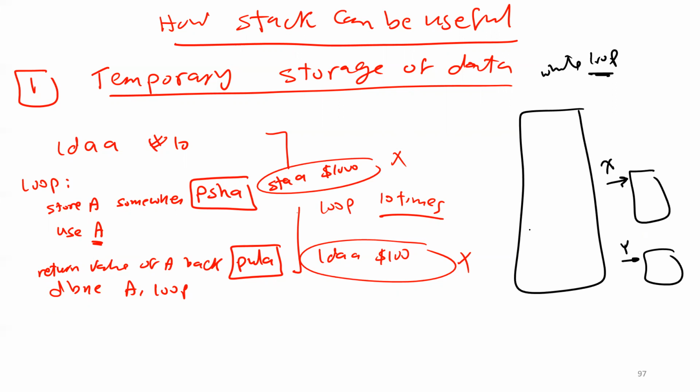However, here, as you remember, we tried to do multiplication. However, the multiplication is going to store the result in Y, or you have to put something in Y. So the multiplication instruction here is going to destroy your pointer. So the way we did it in the last lab, I told you, you have to store it in some memory location. For example, you can say here, store Y at location 7,000.